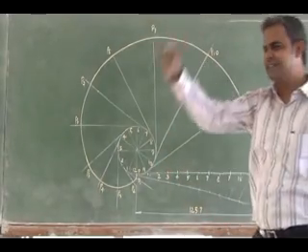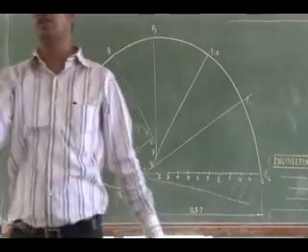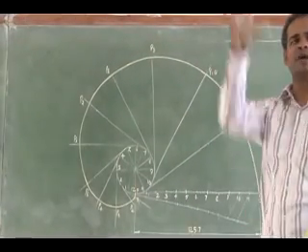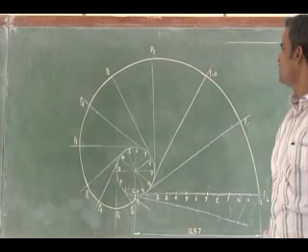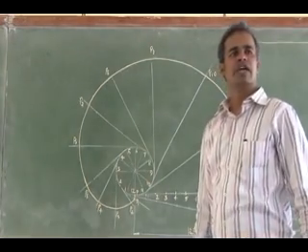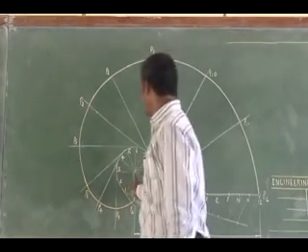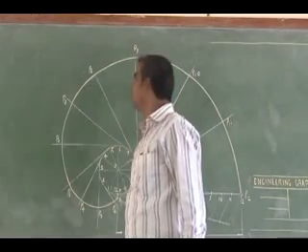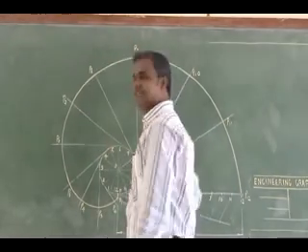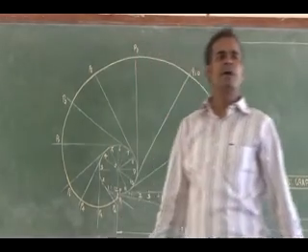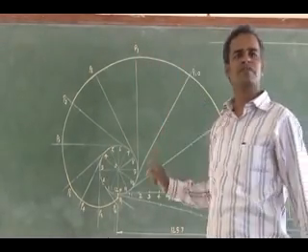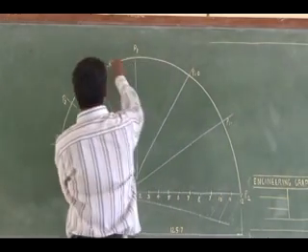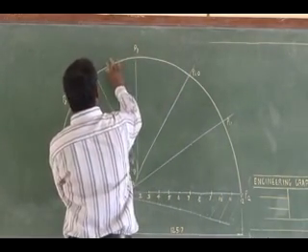Right? Now the tangent and normal, the point location is given. What is the distance of the point from the center? 90 mm. You measure it in your compass, in between which 2 points. Check 90 mm from the center, approximately. See here, listen. The 90 mm point from the center falls in between P8 and P9.